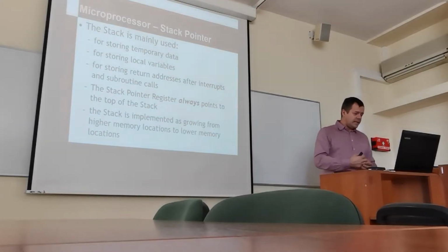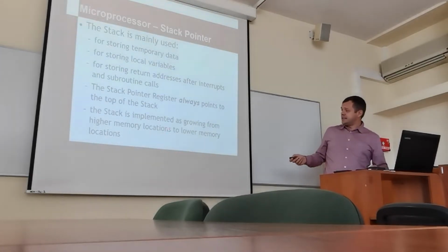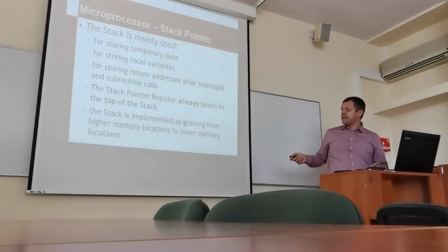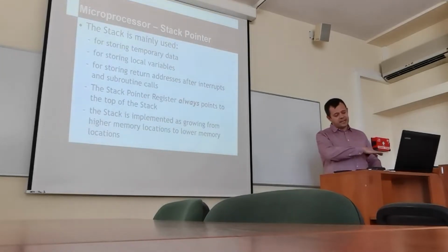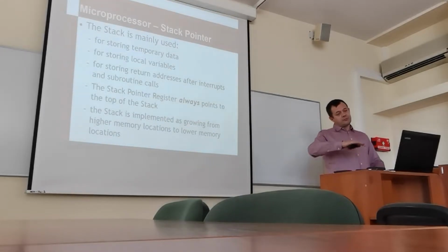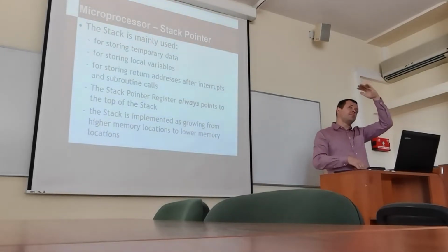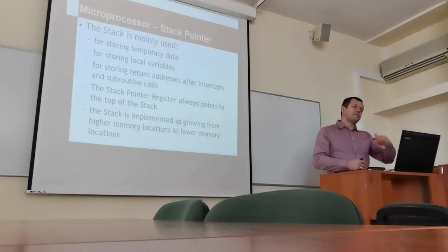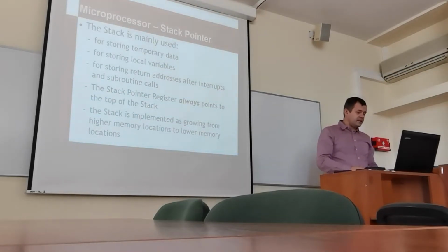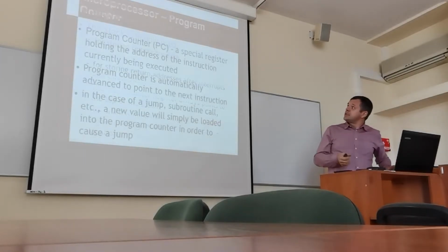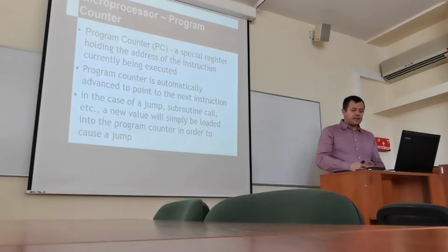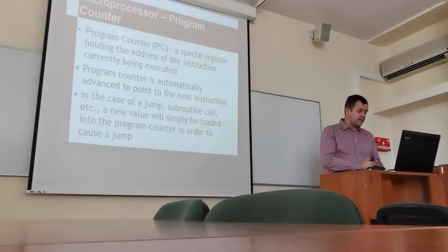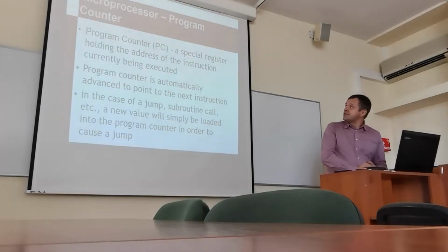So the stack is implemented usually as growing from higher locations to lower memory locations. So it's also usual that we put the stack at the bottom of the memory, so it's growing up, and then at the same time we are using variables on the top of the memory, and we pray that they don't meet, because it leads to a catastrophe. But more about the stack, and what's the difference between stack and heap, I think we will gradually extend during the semester.